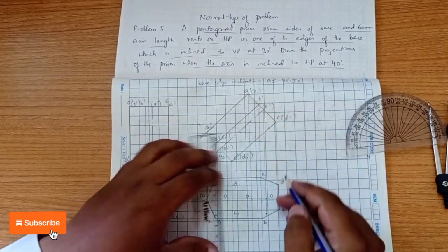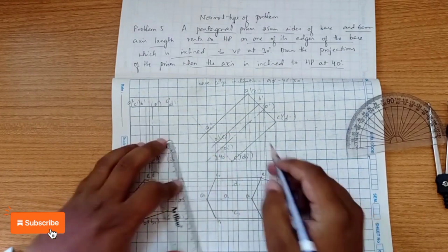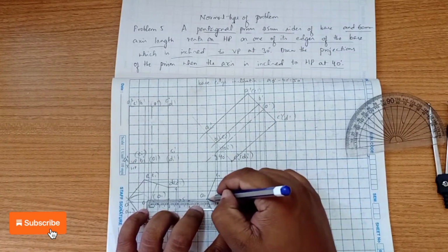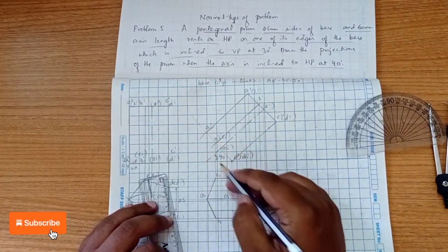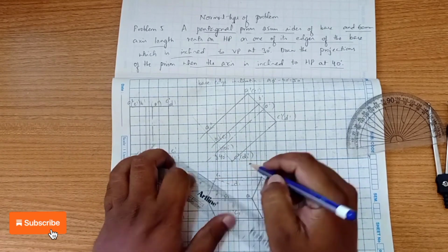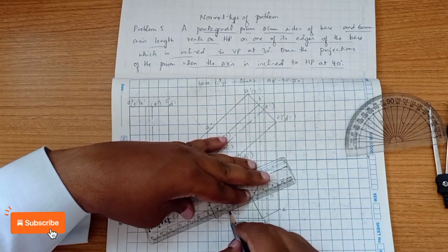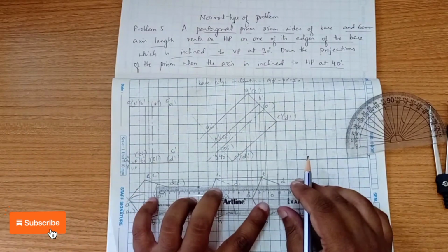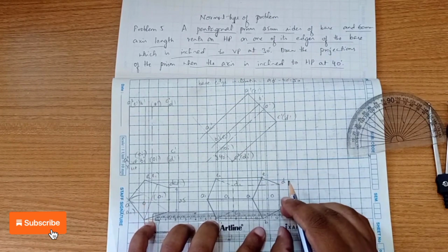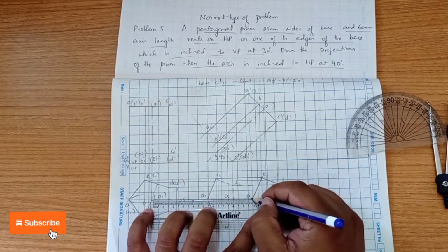Now the top face is visible, that's why we get the continuous pentagon here. And then the edge, you see A dash and A1 dash, that is also visible, so continuous line. Now you see the bottom face is not visible from the top view, so that's why a part of the pentagon will be written with a dashed line. Okay, now the slant triangular rectangular face D1 and C1 is not visible from the top view, that's why it is also a dashed line. Okay, so part of the axis we show it.